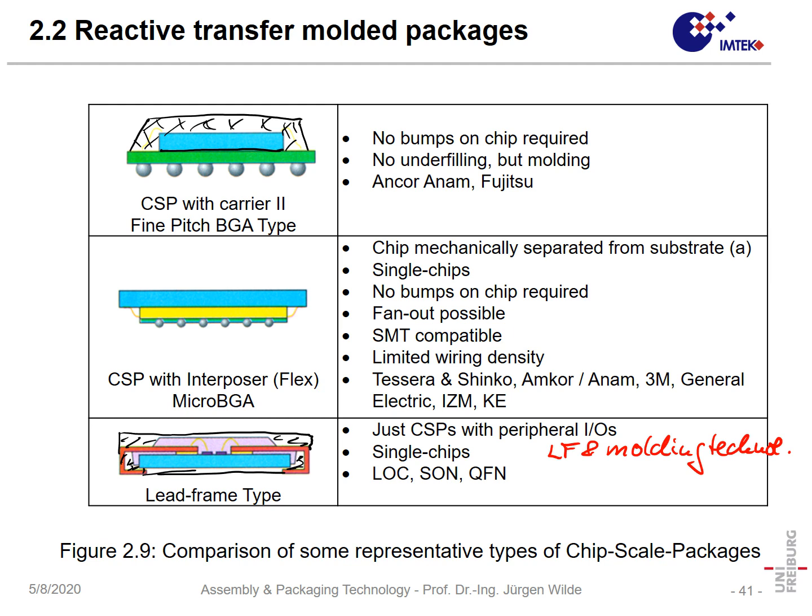That is important because often companies have their equipment and they would not like to change all of their equipment, but they would like to keep a technology which they know, where they have the machinery, and then the easiest is just to change the design of the devices and not to implement a completely new technology. Something new would be the chip scale package, which is made as a ball grid array type.